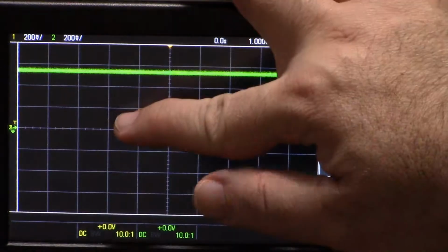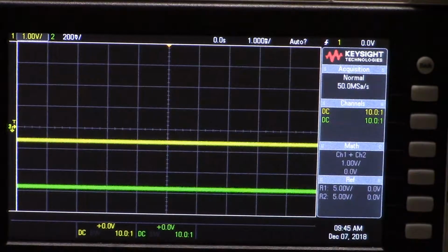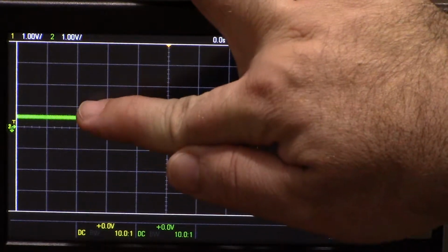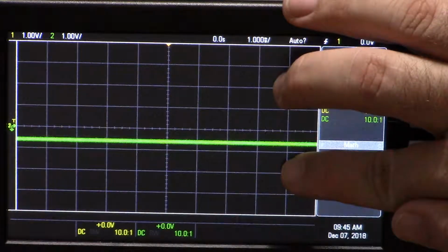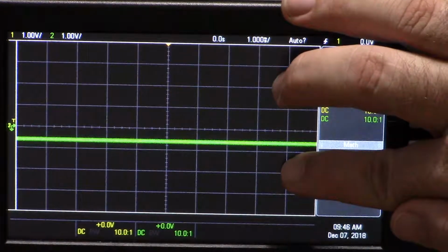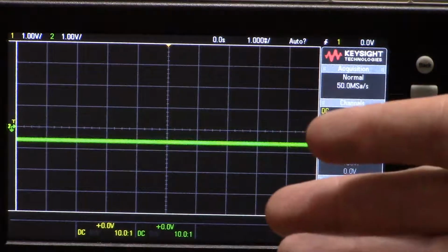2 volts peak to peak, so plus 1 volt, minus 1 volt. And again, I'll shrink it down so that 1 volt, see this divider here between my fingers is 1 volt, and you can see that it's going up and down at absolute maximum volume at less than plus 1 and minus 1. So 2 volts peak to peak should be safe.